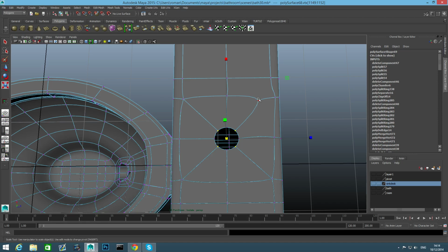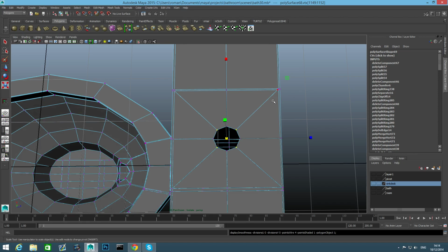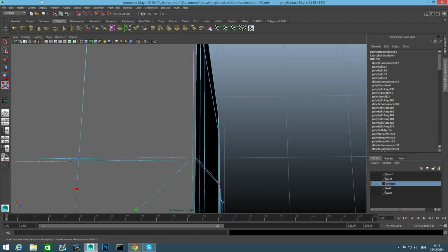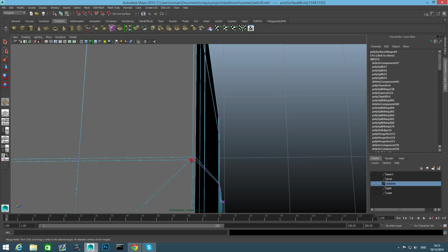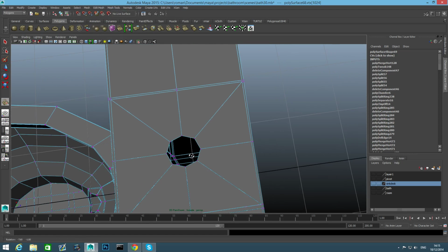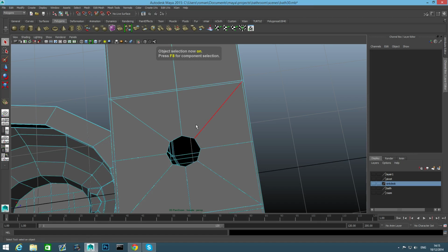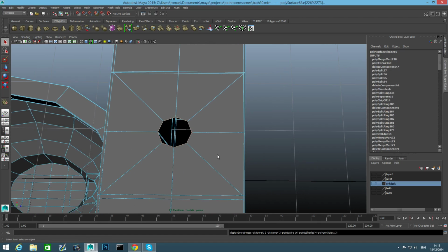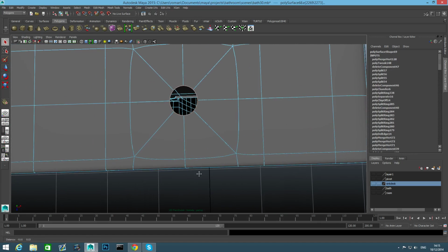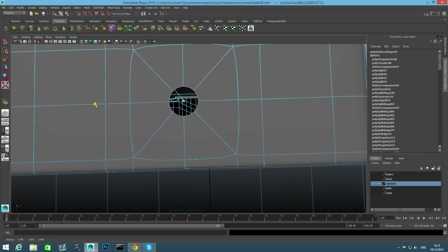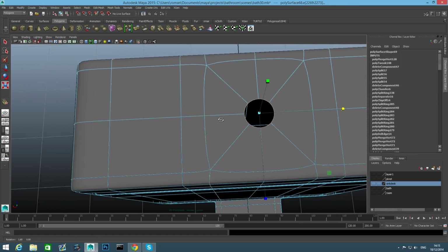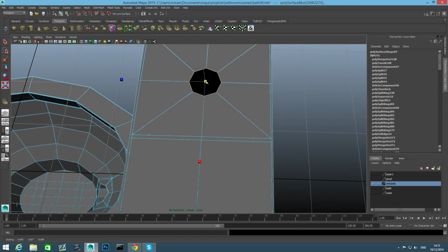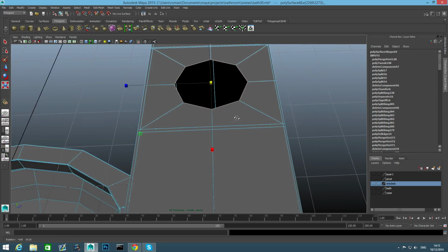Looks like this vertex here hasn't been attached correctly when I used the multi-cut tool. So I'm gonna zoom there, take the merge vertex tool and attach it that way. Press F8, right click, choose edge, switch to selection tool, double click on this edge, press 3 again, and see that I can maybe open this a little bit wider on that axis, and I'm going to press 1 and uniformly open them to about something like so.